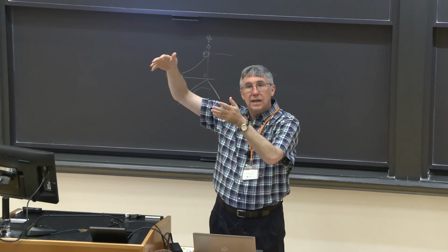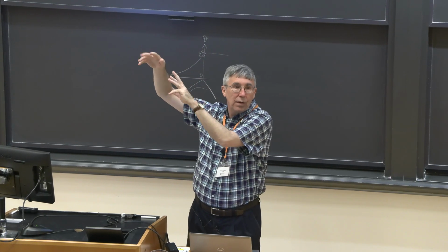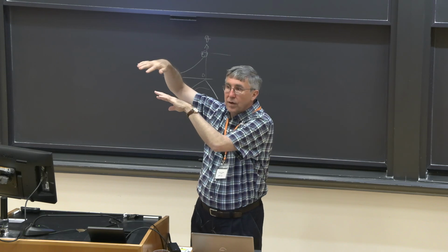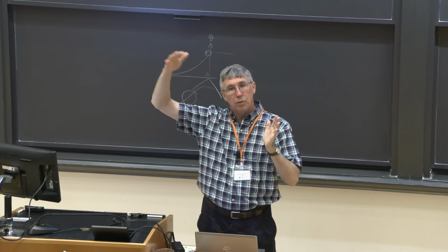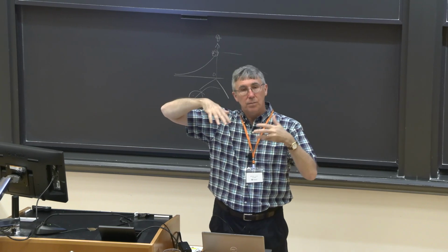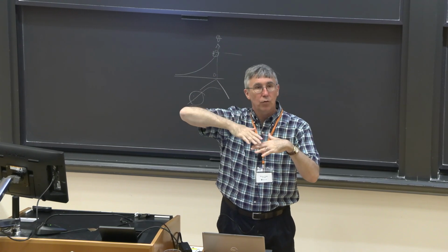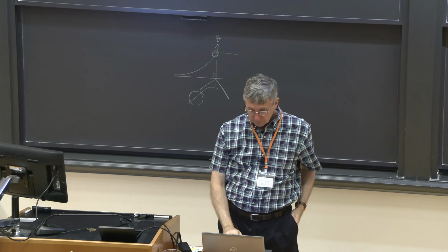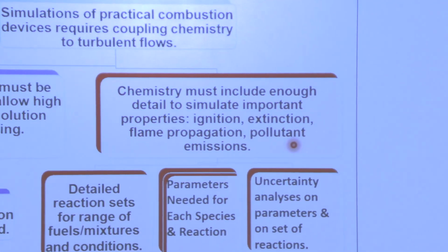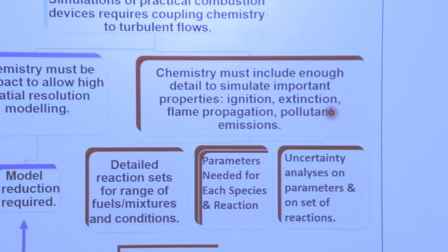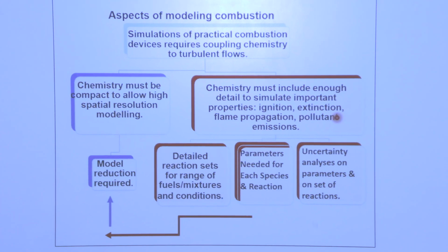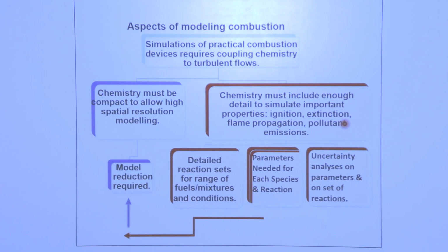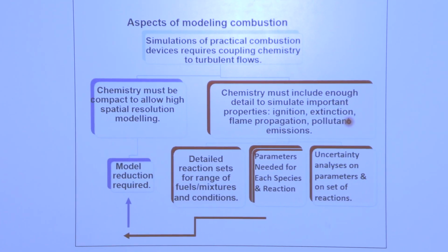And then as the reaction proceeds, all the fuel's consumed, and all you have is a lot of exhaust and secondary products. And you have to have all these reactions of secondary products. And so if you wanted to simulate that whole thing with one chemistry model, you'd have to be sure that all those reactions are relevant for all the different stages of what happens. This can be quite a problem because the number of different reactions you need to have in your model could be quite enormous, and it's hard to make sure you didn't miss one, and hard to make sure you have good expressions for the Ks and the thermochemistry for each one.